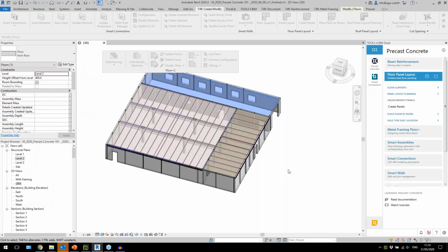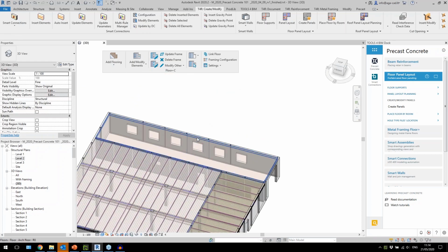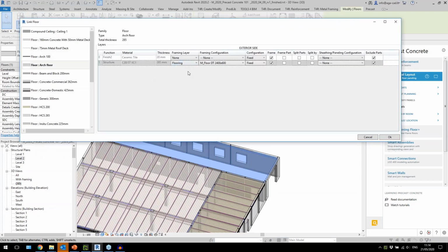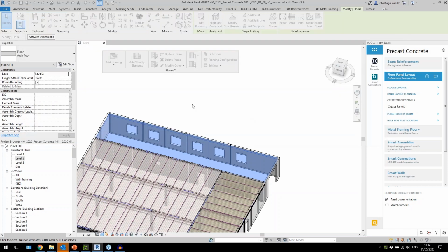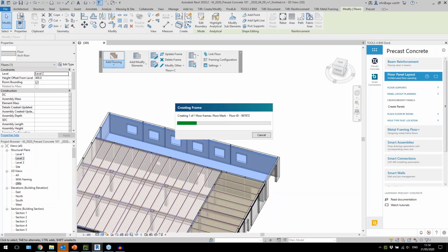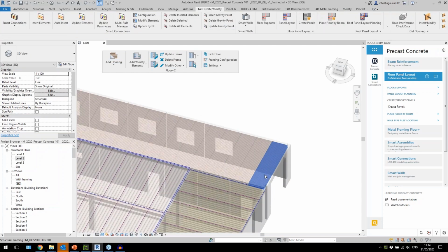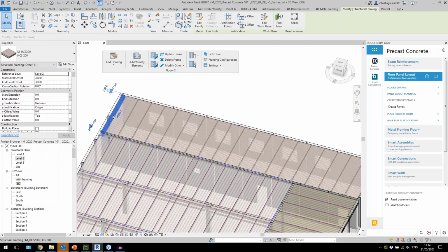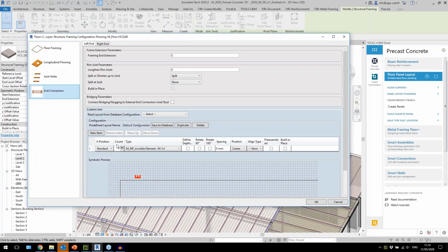So for example, what I will do now, I'll select this one and this floor, and then it has 2 layers, and I will say that in this layer I want to place this family. Okay, so I'll do that, and then by that configuration I will place these families. So we'll see I'm just now creating layout of structural framing elements. They are disallowed joints, so you don't need to do that manually. Then the last piece is automatically smaller, but again I can